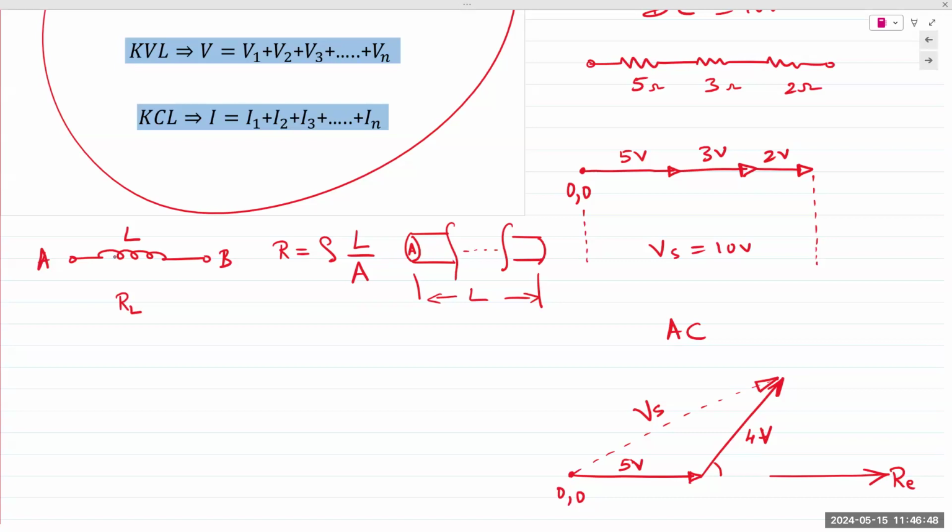Okay. It's physically the same component. You cannot separate it out. Physically, it's the exact same component. Make sense? You cannot separate it out. Electrically, we represent it as an inductor in series with that resistance between A and B. This would be L. This would be RL. And this is what you're doing in this week's lab.